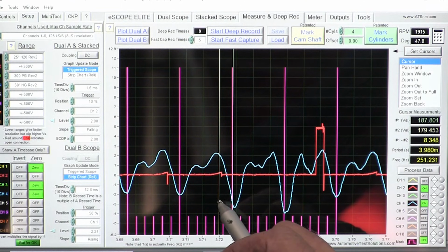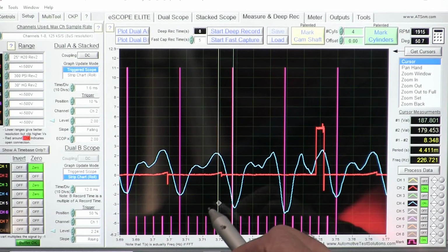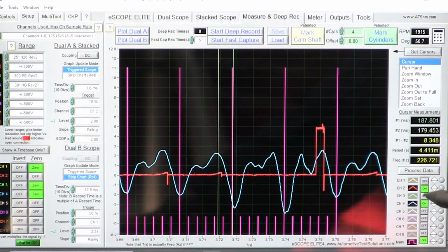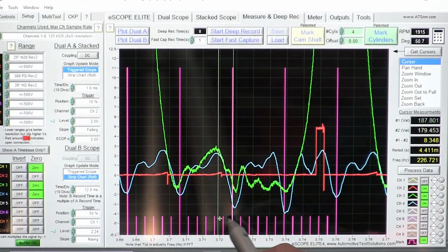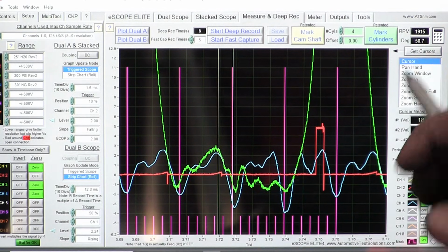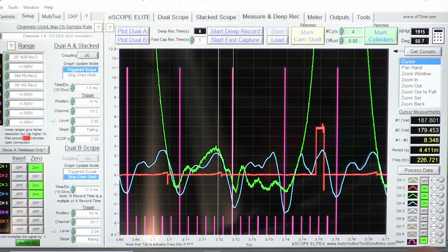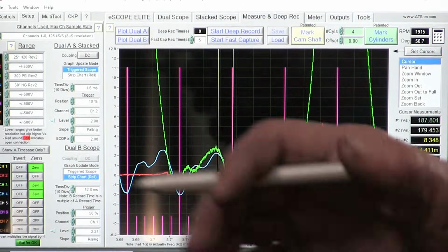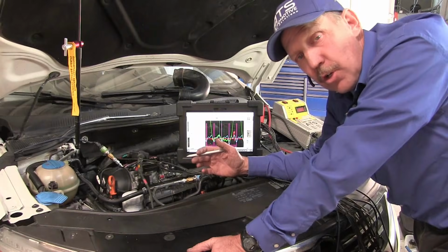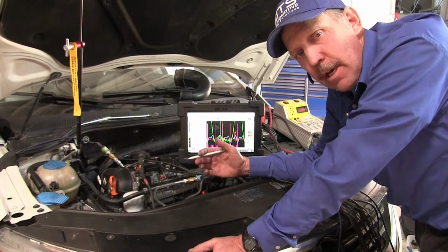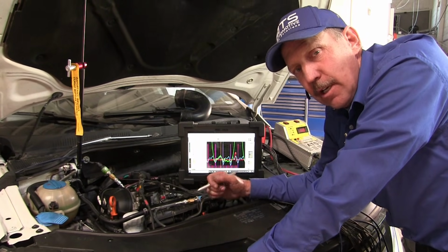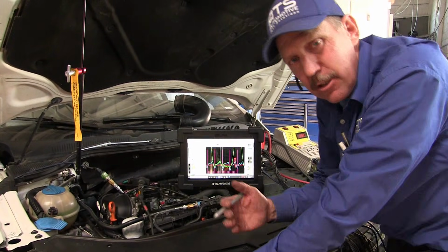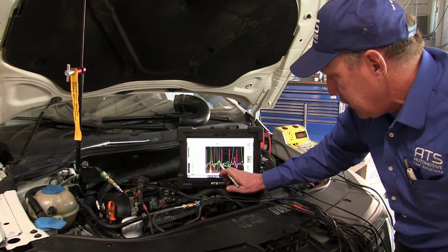Maybe even just a little earlier, maybe about there. So basically that's about where the valve opens, and I can follow that that happened at the exact same time in the cylinder. So that valve is opening this much, and we can see the difference is 50 degrees. So that intake opened 50 degrees early. Now that's close to what the cam timing said. Remember the two targets we saw, the crank and the cam? So the crank and the cam had an issue, and they were about 60 degrees, so 50, 60 degrees. We're seeing this repetitive. So that intake cam is opening way too early.